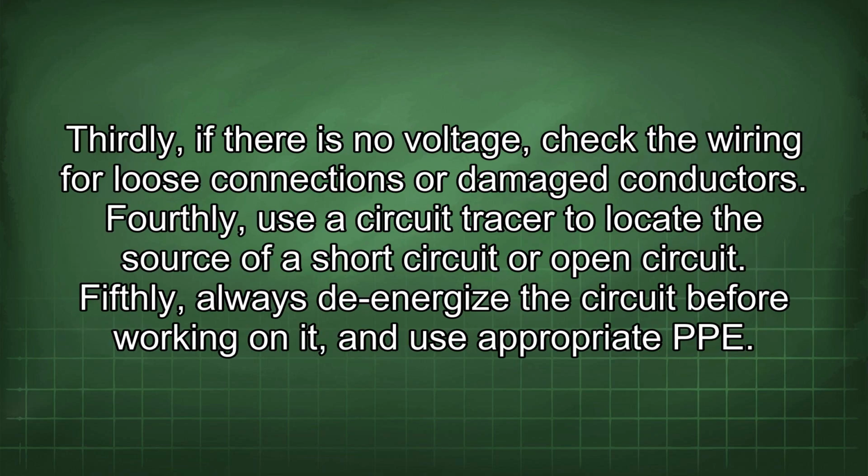Thirdly, if there is no voltage, check the wiring for loose connections or damaged conductors. Fourthly, use a circuit tracer to locate the source of a short circuit or open circuit. Fifthly, always de-energize the circuit before working on it and use appropriate PPE.